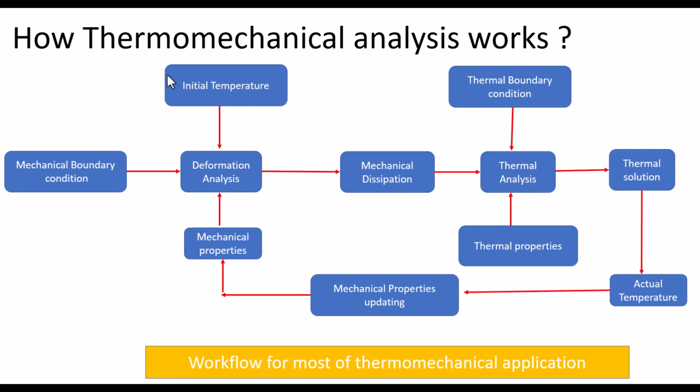But whenever the mechanical dissipation is happening, we have to solve the problem as a multi-physics problem, because after each iteration this whole loop is going to be carried out, and internally we need to find some type of equilibrium solution after each iteration. So again, in APDL there are two ways to handle even this two-way coupling type of problem.